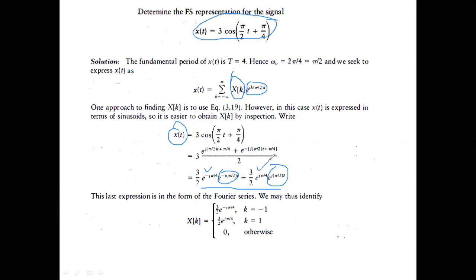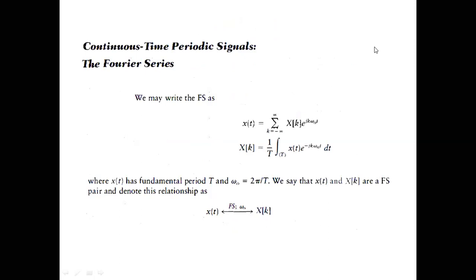So what you are trying to do here is represent a time domain signal in terms of the fundamental frequency and its multiples. What are these, by the way? e to the power j theta. These are all complex exponentials. So you are trying to represent a signal x of t in terms of complex exponentials and its harmonics. What is the contribution of omega naught, 2 omega naught, 3 omega naught, 4 omega naught, and so on? You saw this even in the beginning when we took the Fourier transform example.